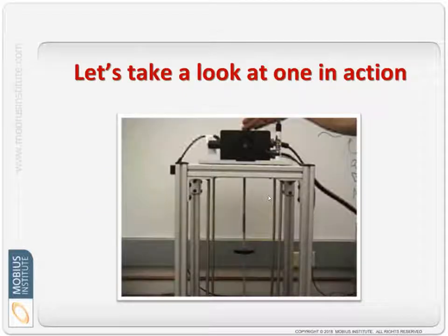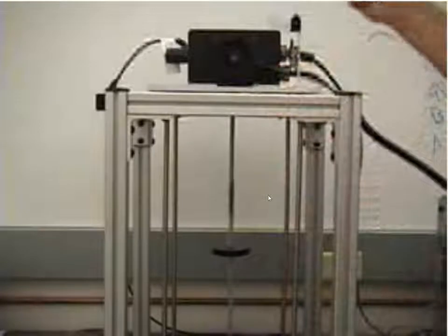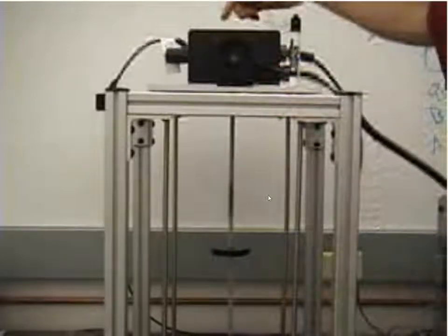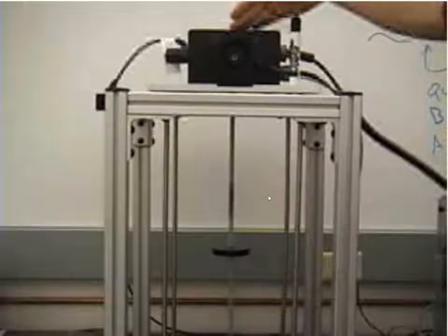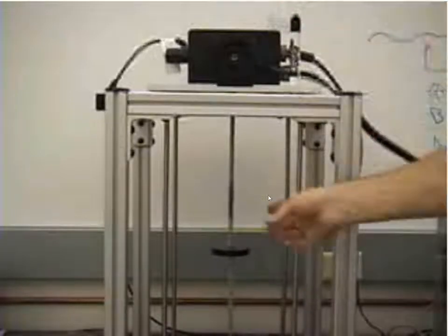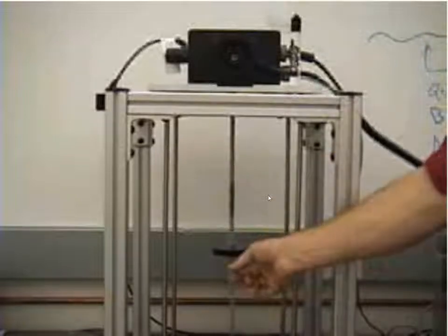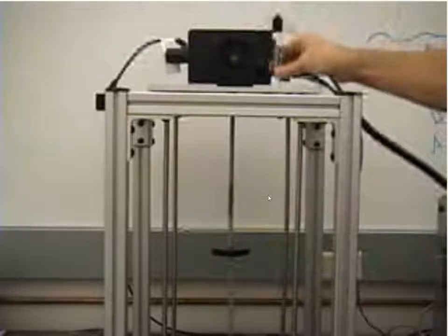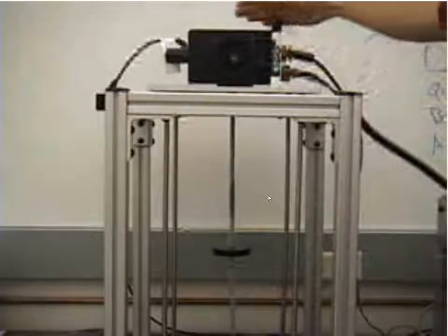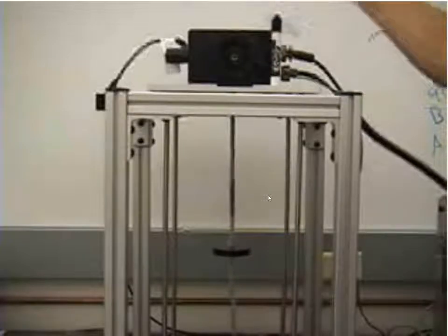So here's a little video that sort of shows one in action. Here we've got another single degree of freedom spring mass system with a forcing function. In this case we've got an imbalanced mass which is being spun. Although we're spinning it with fairly significant vibrations, it's not moving much because we've got a tuned spring mass damper right here. So its resonant frequency is exactly the speed that we're spinning at right now. So Bob, the maintenance man here, can stand on the top of the building with the imbalanced air conditioning unit and not experience too much vibration.